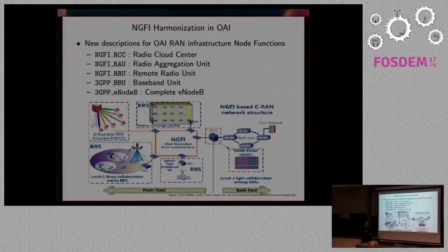So you might have at most a 30-40 meter optical link. In the new networks, that 30-40 meters is going to become 10 kilometers. And these nodes here, or potentially already the ones closer to the central office of the operators, are going to be doing a lot of signal processing for a whole network. So that changes the way you actually do things. It changes the way you architect the signal processing system.